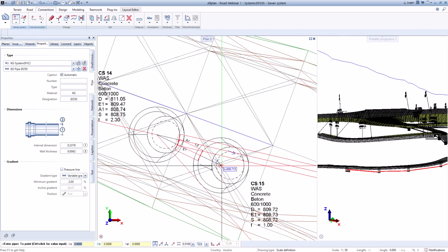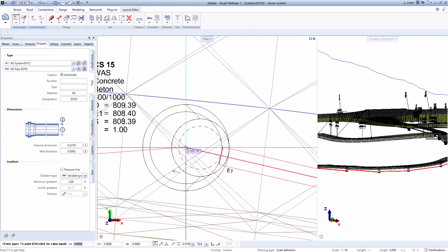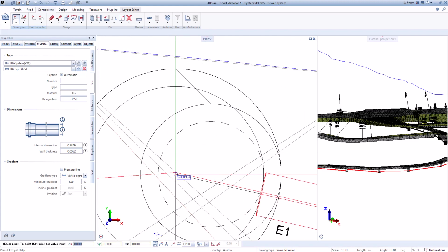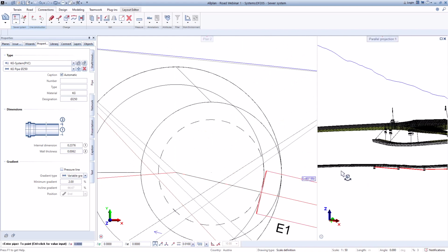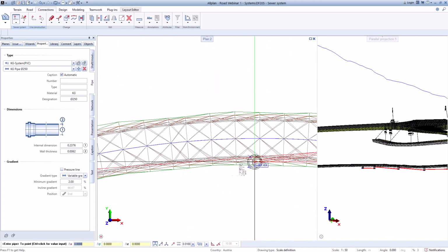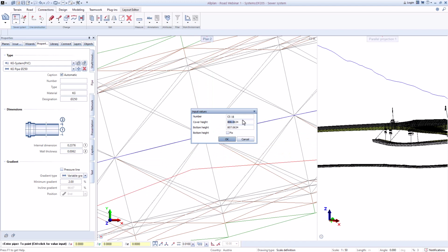Okay, in the right side you can always see what is already done. In the 3D view, again, always click Control and click on the point so that this new window opens where you can input your values. The values are set so that we are up on the top of the street, and the bottom where we connect the pipes. The shafts are between 2 and 2.5 meters.